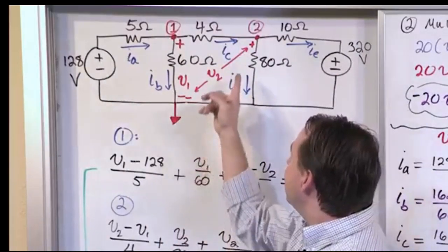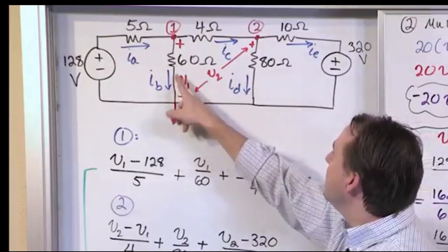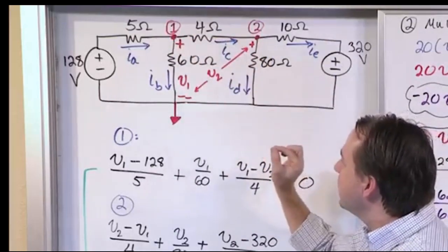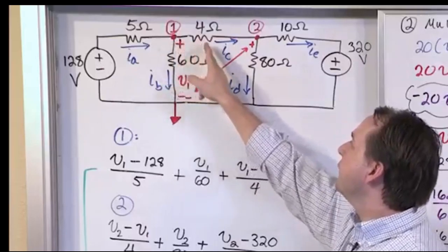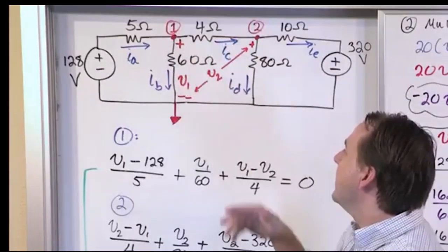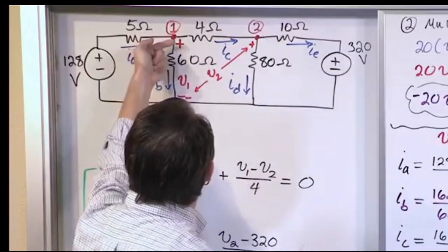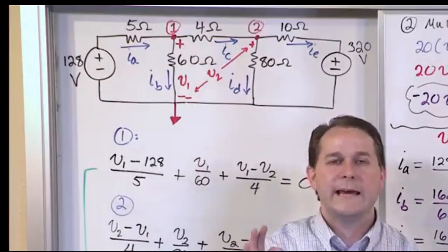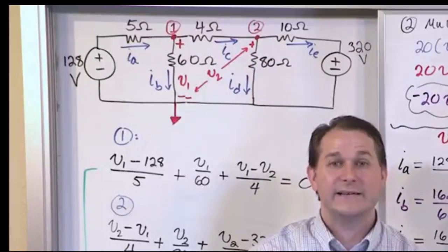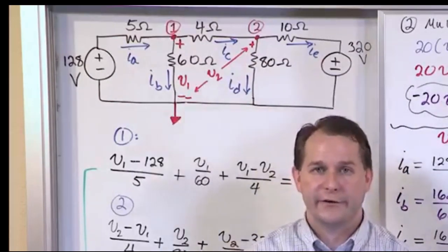And so when I make this guy over here, I'm assuming V1 minus V2, I'm making an assumption that V1 is bigger. So when I subtract this guy off, the current is flowing in this direction. I have a voltage drop across 4 ohms in this direction, plus minus. So when you subtract two voltages, you're making an implicit assumption that one side's higher than another, right?